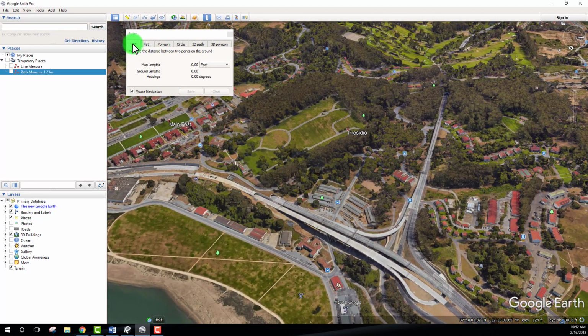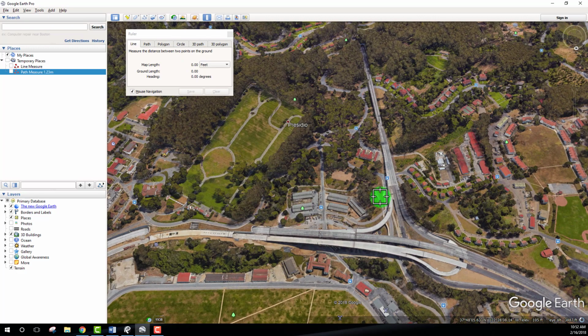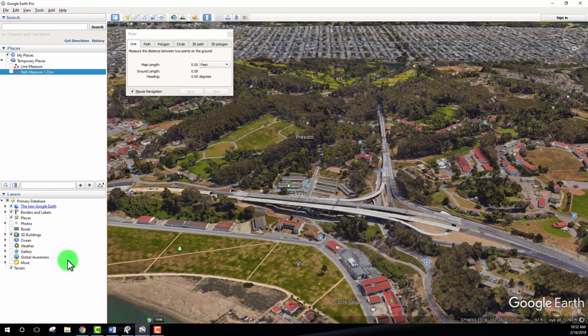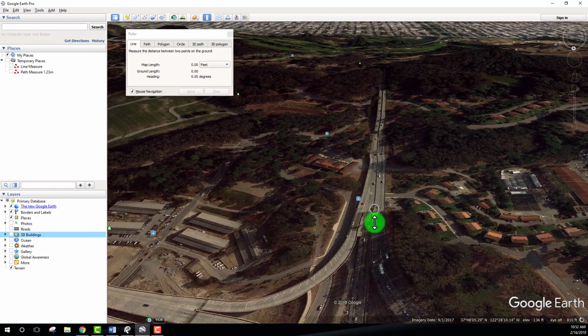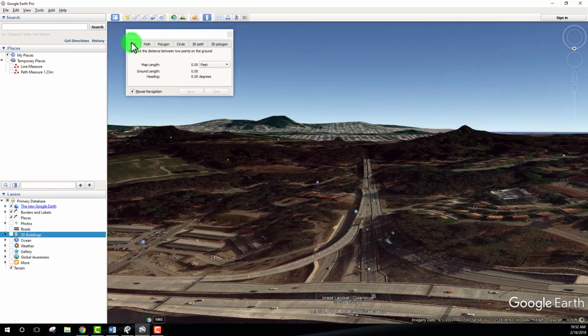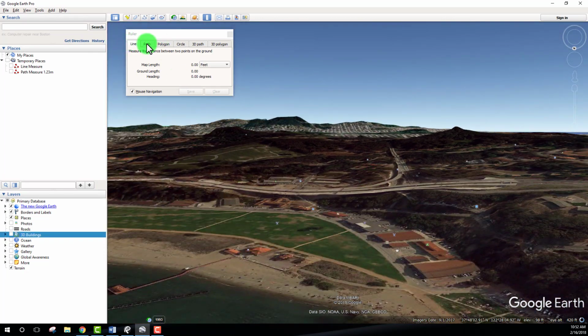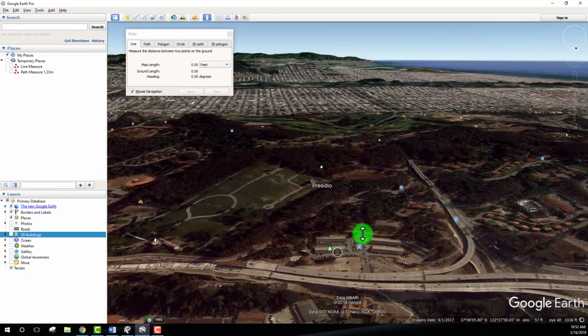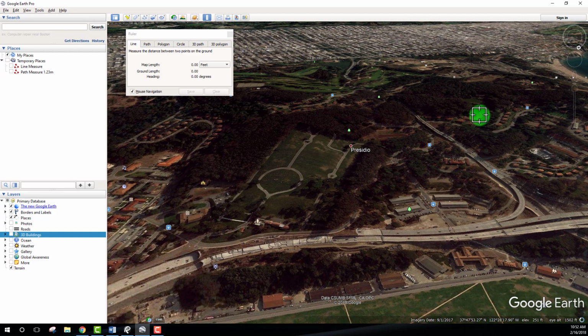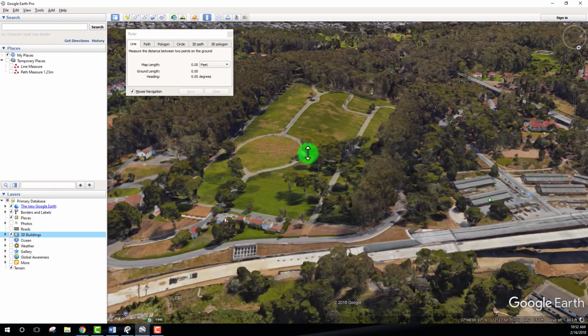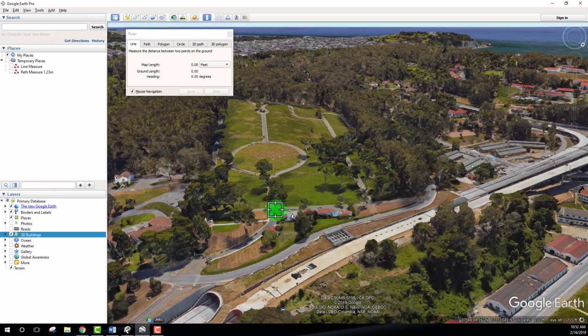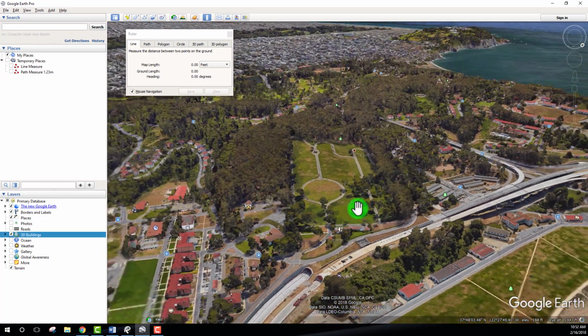So the line is essentially our most basic measurement, and again, if you turn off your 3D buildings, this is really the surface that we're snapping to anytime that we're using these four inputs. So it's really important to understand the difference between this surface when you're doing these measurements and having those 3D buildings turned on, because in some cases that could drastically change your input method.